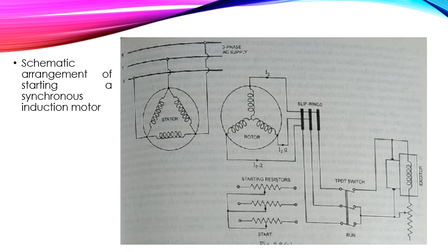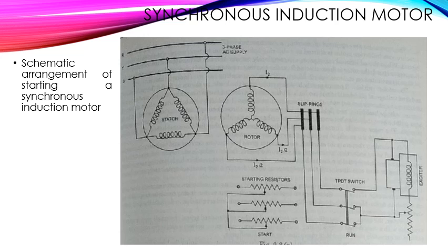Now we'll see the typical circuits for synchronous induction motor. So first we'll see the schematic arrangement of starting a synchronous induction motor. As shown in figure, the synchronous induction motor is started as a slip ring induction motor by inserting resistances in the rotor circuit through slip rings and TPDT switch.